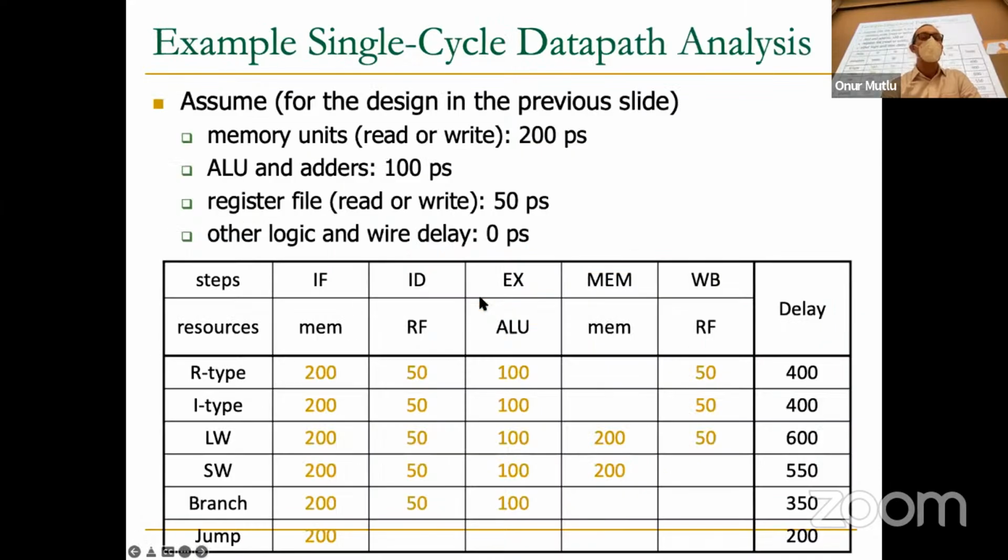So assume for this design, instruction fetch, where you access memory, takes 200 picoseconds. Instruction decoder and register file access takes 50 picoseconds. ALU and adders take 100 picoseconds. Memory here takes again 200 picoseconds, and write back, register file write, takes 50 picoseconds.